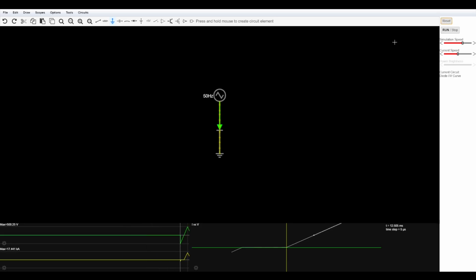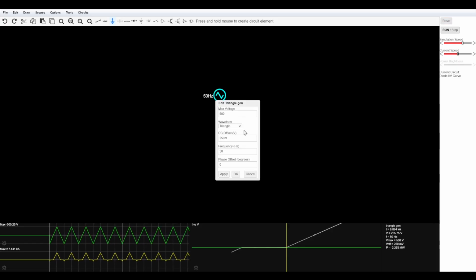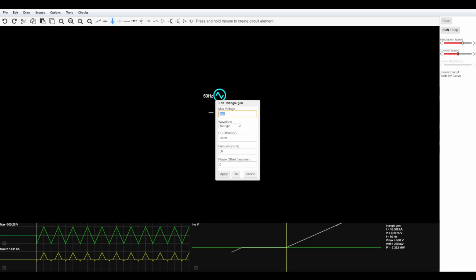There we go. We actually see the breakdown for some reason with this model isn't starting to kick in until negative 400, which sounds wrong for this diode model. I should really look it up. But this is the kind of curve. You've got the forward. Now we've made such a distance that we can't really easily see that. But we'll change it back. We'll do 10.